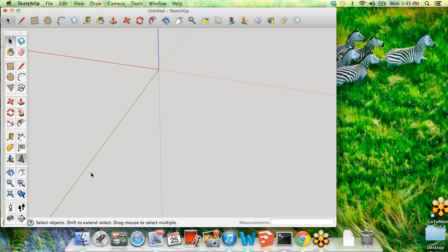So you can use freehand to try that out, but when you're building and modeling with bigger shapes or something that you want really accurate or to have clean, sharp lines, you're going to be using more of the combination of the arcs and the circles and the different shapes that SketchUp gives you, along with combining them with the push-pull and using move as well.